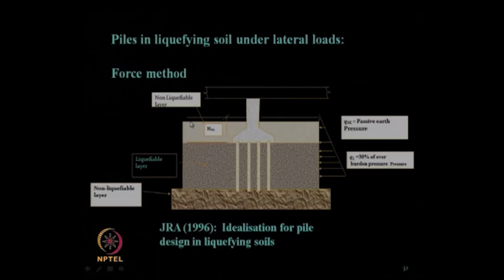We know how to estimate the liquefaction potential of any particular soil, that we all know about, and it is followed by some soft layer, or some layer which is supposed to be prone to liquefaction under certain magnitude of earthquake. Okay? Then followed by another stiff layer which is non-liquefiable. So, basically if you have an end bearing pile, you will take it and end it up in a strong or stiff strata or even rock, right, soft rock or dense strata, dense sand.